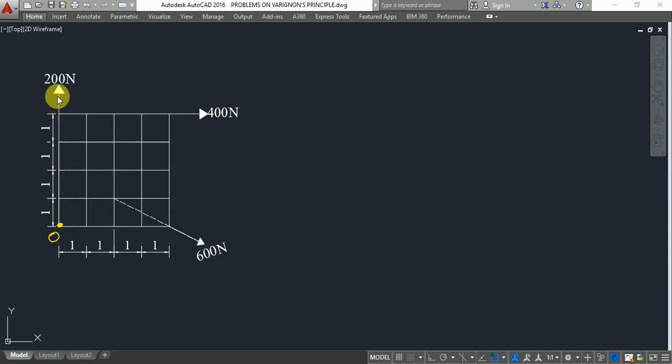See here, because of this force, if I choose this point, let me write it as O or A. About this point, how is the force producing the rotation? Since this force is passing through the same line of action, there is no perpendicular distance. Force into perpendicular distance is 0, right? This line of action will pass through this point. If I come to this force and extend its line of action here, what is the perpendicular distance? The perpendicular distance is from here to here, and this is the force acting here.